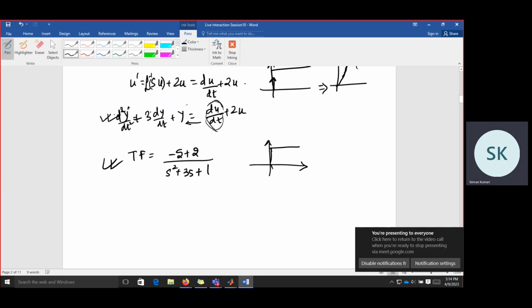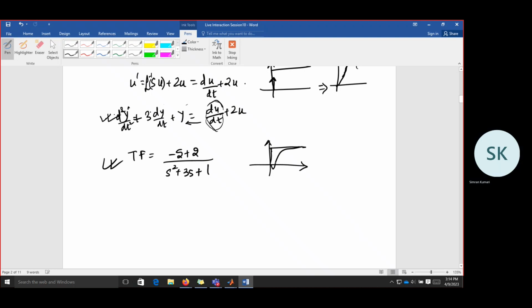What we see is the undershoot initially and then the system reaches this value. This is not a behavior that we want, because we want the error to be minimized, the step response tracking the input. This is one thing that is present in a system having a right half plane zero. So this type of system is called a non-minimum phase system.